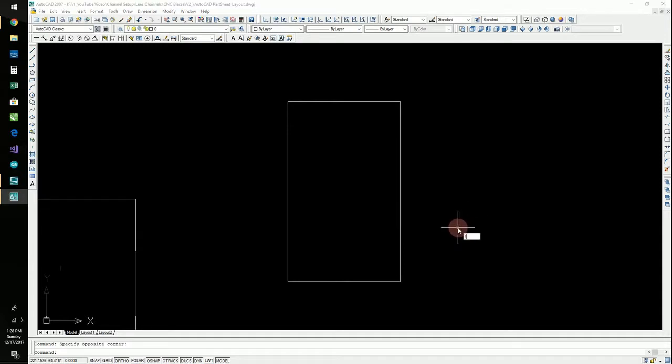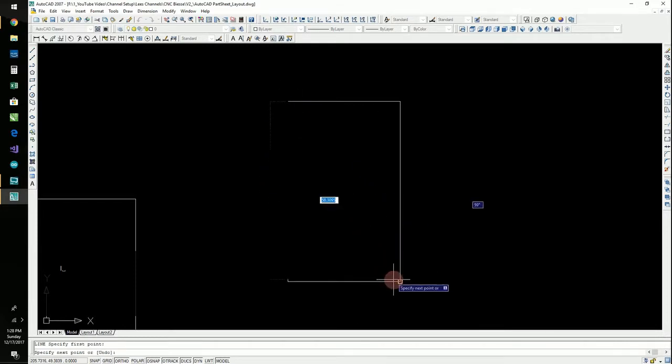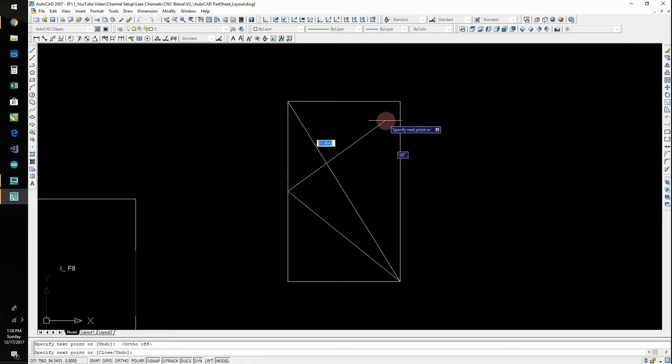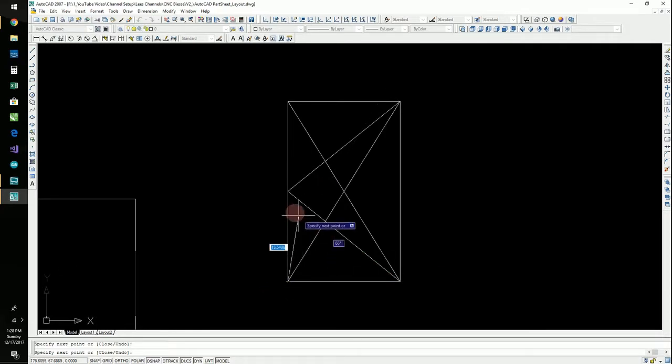Let's say I'm going to do a line. I'm going to snap to there, there. I'm going to go out of ortho. So then I'm going to go to the middle. I'm going to go back here, and escape. So now this is 30 inches across this way, but this is 50. So what's 50 divided by 3? Well, it just so happens that if you make that pattern, go back to ortho. I'm going to hit, that's the space bar I'm hitting.